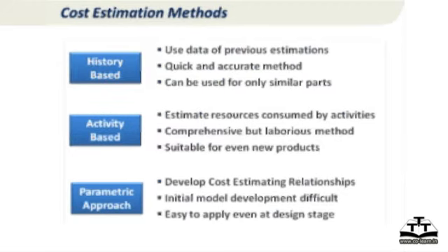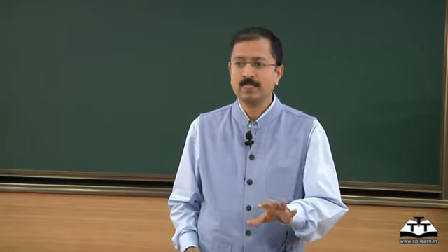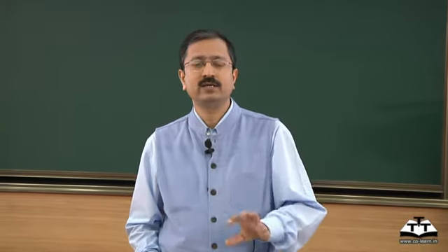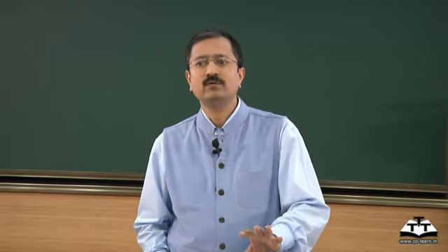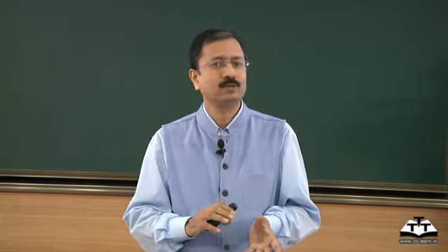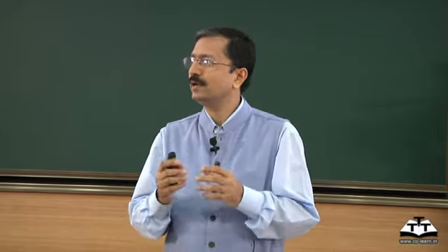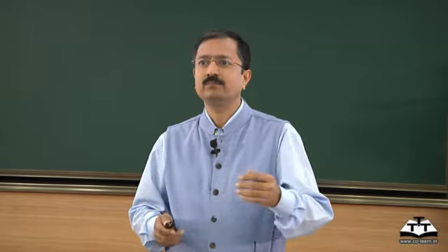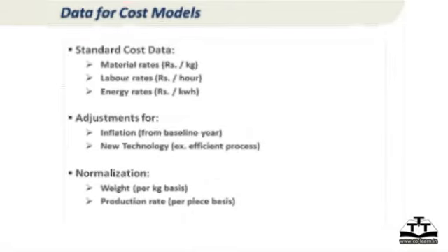So these are three different techniques of cost estimation. One is purely financial, second is more like process planning and resource planning kind of a thing, and third one is purely design parameter based costing. Which is good, which is bad for metal casting? There is no direct answer. Different things are useful for different situations. In fact, we have used a mix of the three techniques depending on which is more easily applicable and inputs are easily available, and it gives fairly accurate and fairly acceptable results.